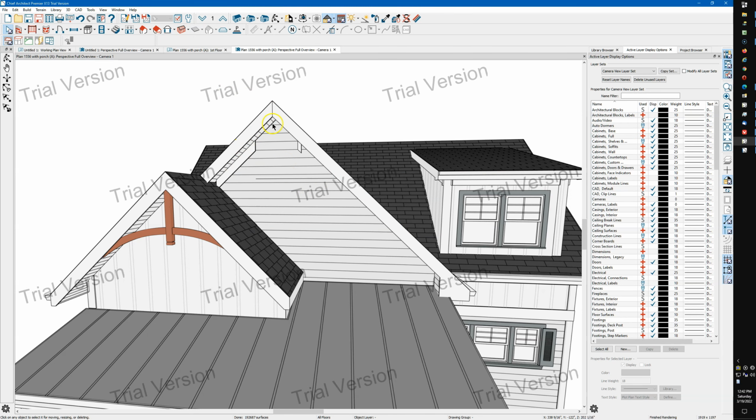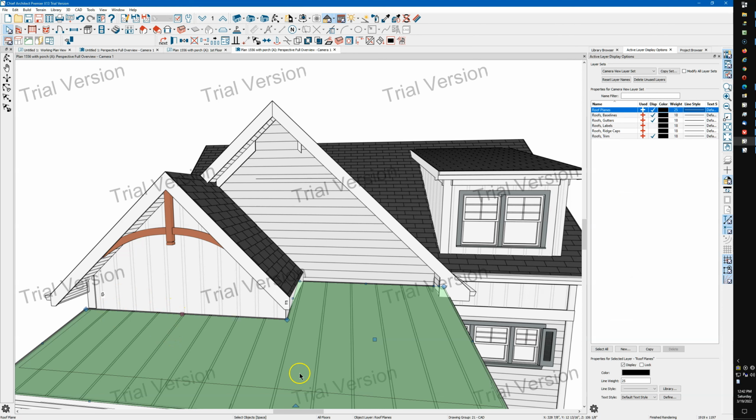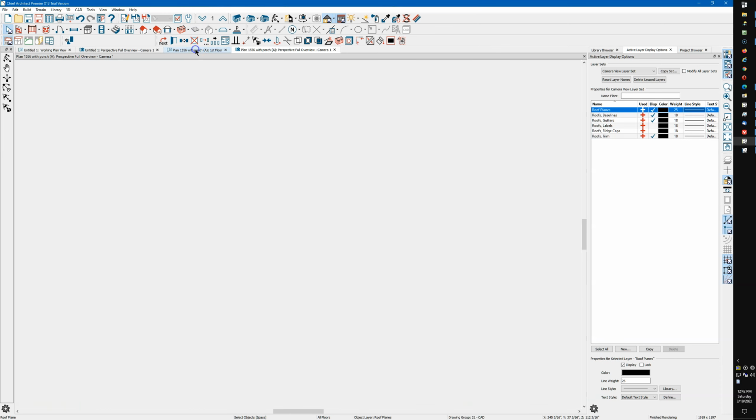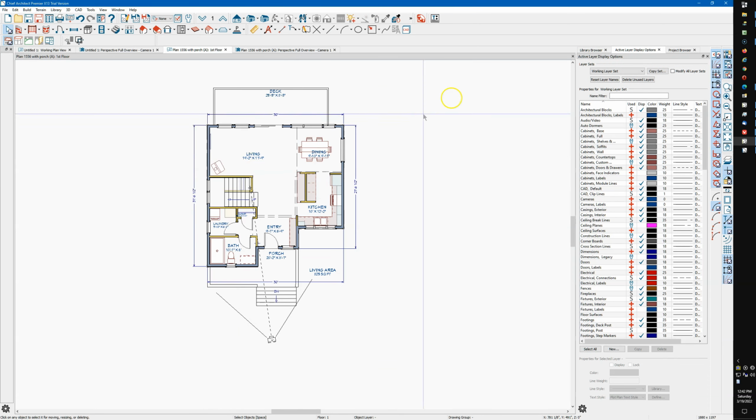And then when you see Frieze like this, it's not building. It's almost always not, you know, there's none here and there's none over here. Not every single time. There's oddball situations, but almost every time you see this problem, it's because of this roof. It's the roof right below, and it's because the roof isn't snapped up against these walls. So let's go over here. Let's turn roofs on.